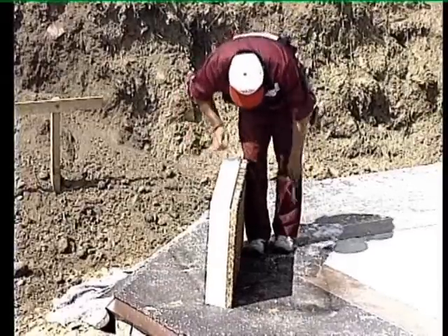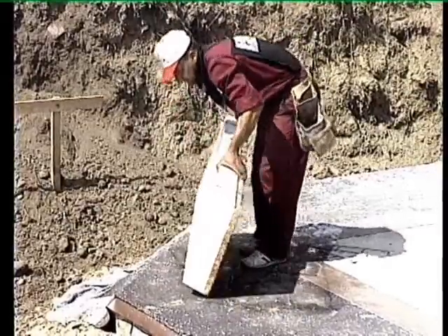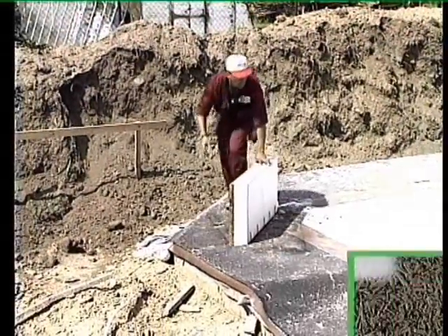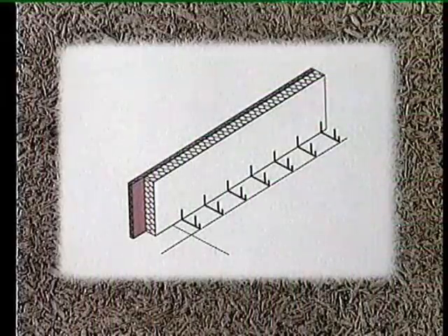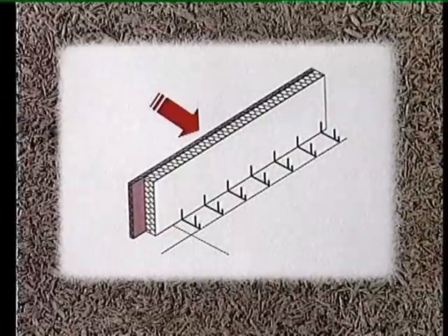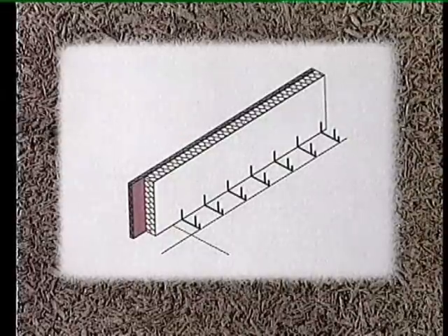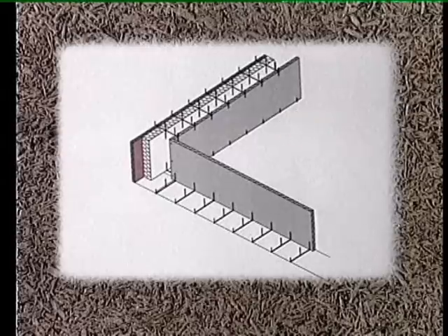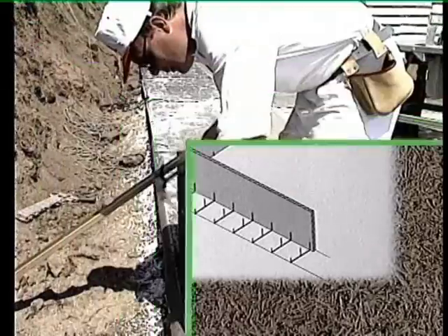Construction always begins in the corner of the building. We lay the first row using one-sided ties on the foundation construction. Boards with a thermal insulating layer of polystyrene are laid from the exterior side of the peripheral walls. Boards without polystyrene are used for the interior walls and for interior load-bearing walls.